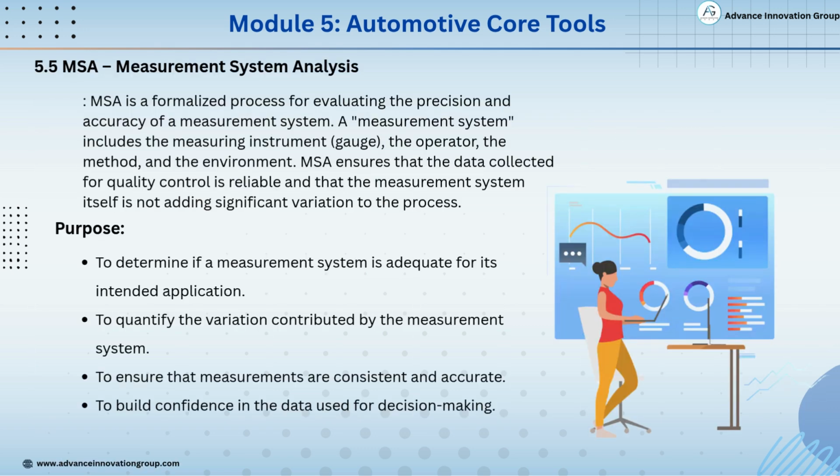This slide introduces Measurement System Analysis, MSA, a critical tool in the automotive core tools. MSA is a structured approach used to evaluate the accuracy, precision, and reliability of a measurement system. A measurement system includes more than just the instrument. It covers the gauge, operator, method, and environment.